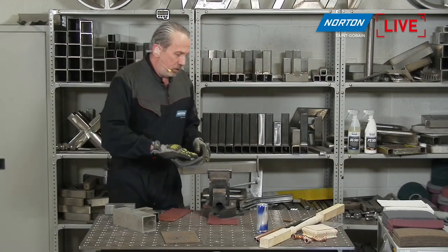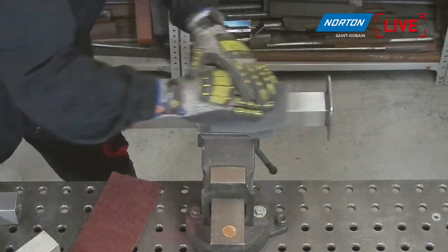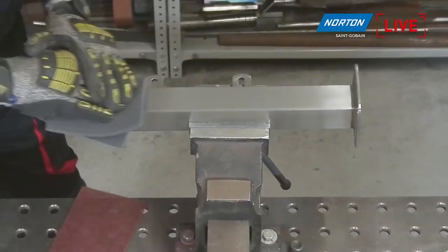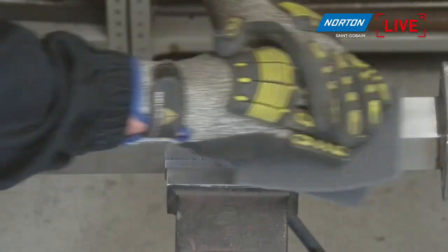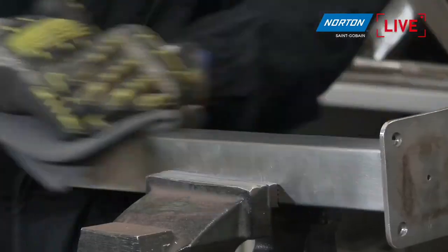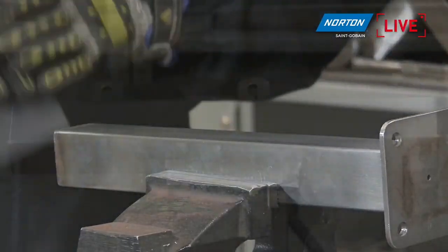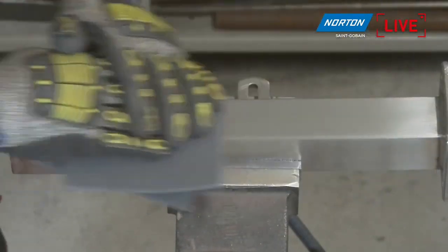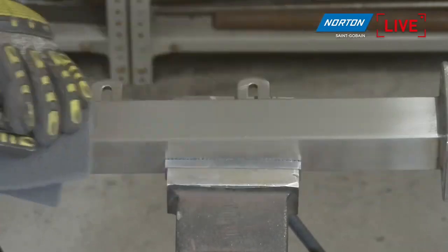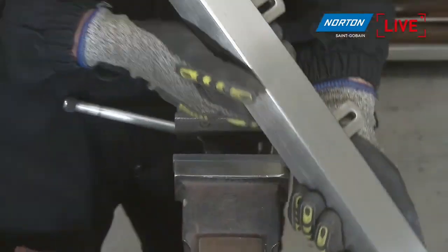Again, really easy to use in exactly the same method. Oh, if I tighten this in the vise properly, it would be helpful. So we just put that in there, and again, rub that down, and that gives us a much brighter finish on stainless than we would get from just the AO pad. So we're just blending all the scratches there, Robin. That really sharp silicon carbide grain's doing a different job to what the previous very fine maroon color pad did. So nice and sharp and great finish.